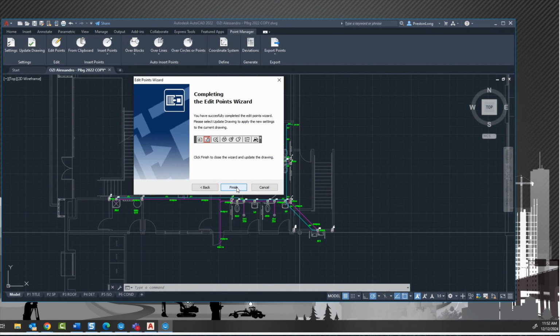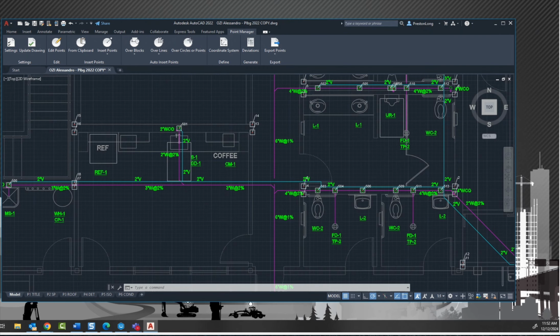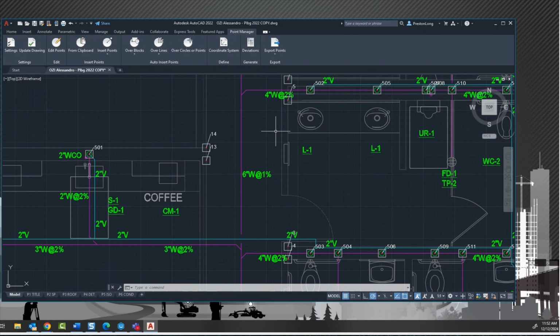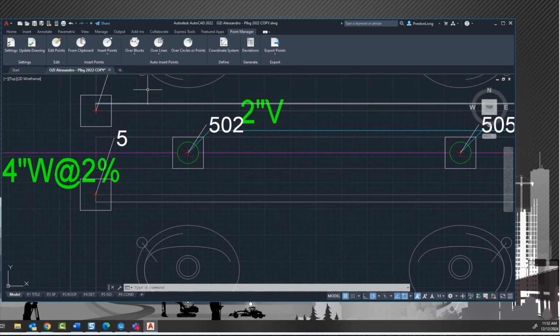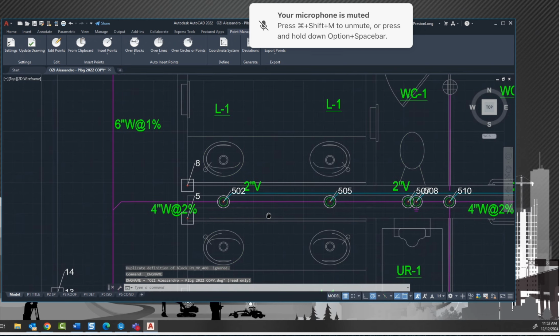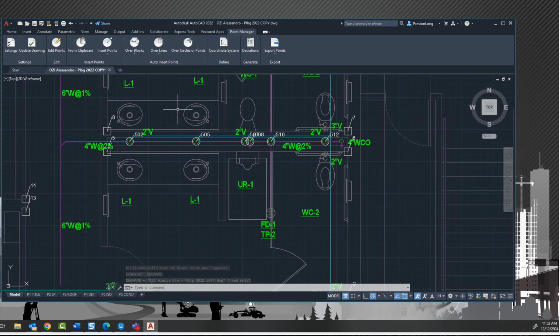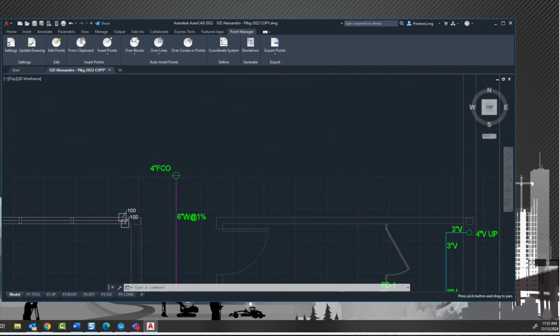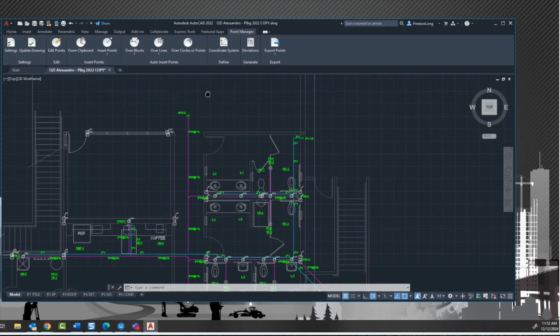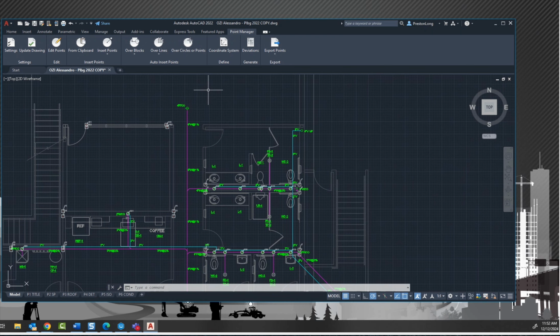Okay. I just wanted to make sure. You do update drawing. Yep. So because obviously those were 2-inch sleeves, I wanted to move those to 2-inch because I was looking at it and I'm like, wait a minute, it's a 4-inch, right? So obviously we can do it per sleeve size. And that's what I did, I just went and edited the group, and then I changed the name to sleeve_2 inch, right?